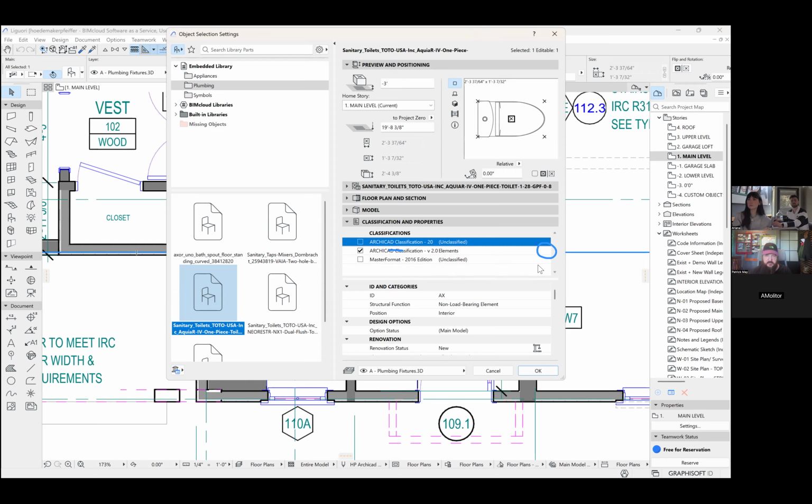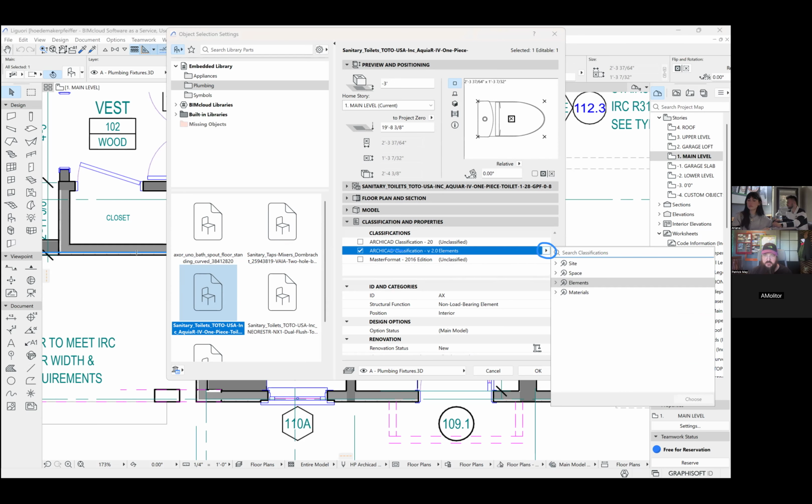Looks like you clicked the line above instead. Yeah, there we go. Okay, so type at the top where it says search and search for distribution. Okay, and you're right. Let's classify everything that we want on the schedule as a distribution flow element. I know it's a little bit confusing, but in the world of BIM, distribution elements get applied to anything MEP related. And we're just going to say our plumbing schedule is going to use this distribution flow element as the identifier. And this does two things.